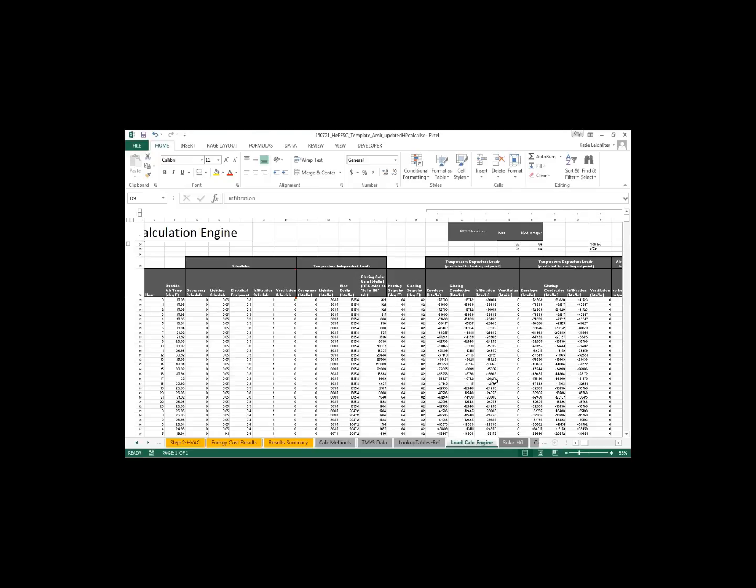I thought it was even interesting that EnergyPlus does all the radiant calculations as well, but it's not including them that early on in its process. So you're seeing the lighting load, which is basically the schedule multiplied by the lighting power density. That's all it's reporting there. Where eQuest is reporting, it's already taking that radiant fraction out and incorporating the zone to get its curve.